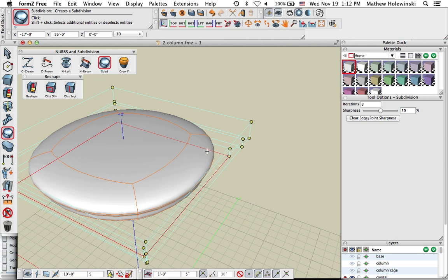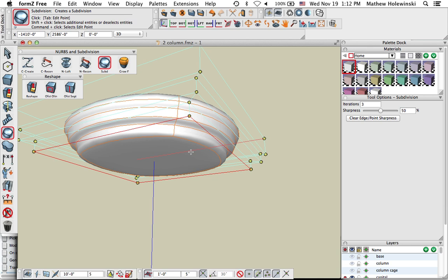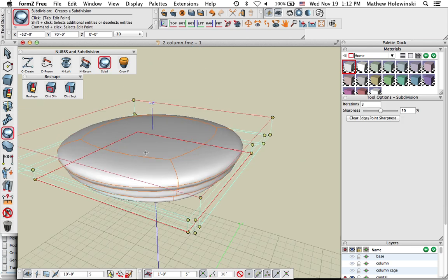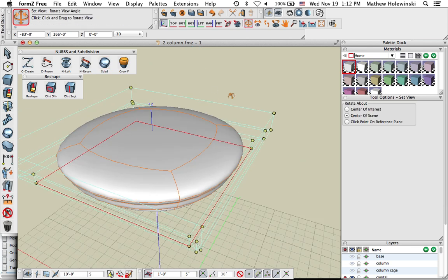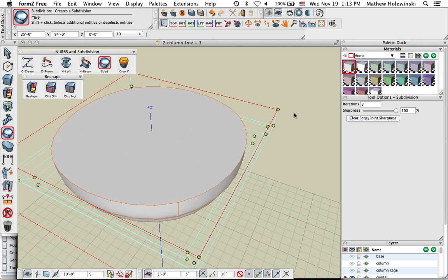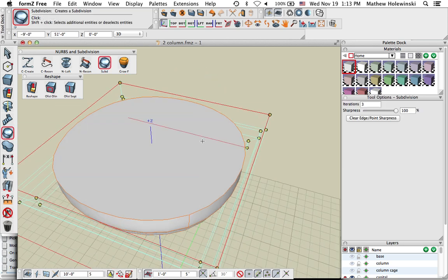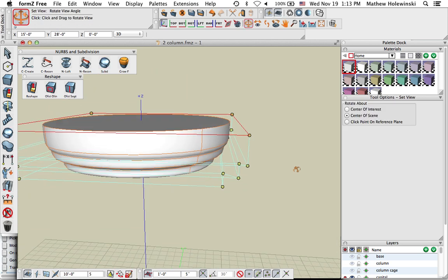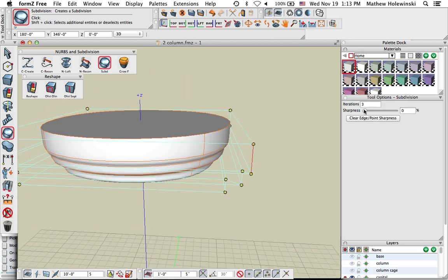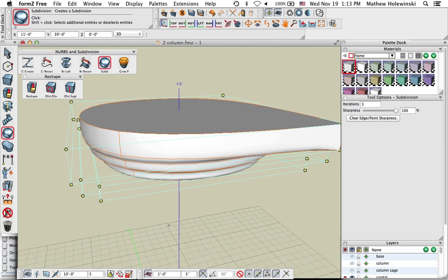But the top of this thing, we want this to be square. And so how can we sharpen this entire top section so that it transitions from a round shape here to more of a rectangular shape on the top? Well, if we select the top face and sharpen that, you can see it's actually flattening just the top face only. So it's still round over here, but just the top face has been sharpened. And so what I'll do is select this vertical edge, and I can actually sharpen that also.